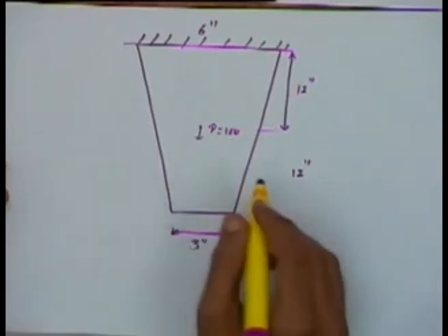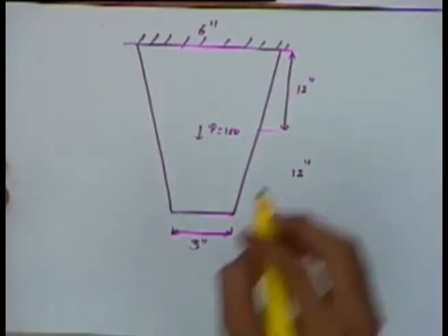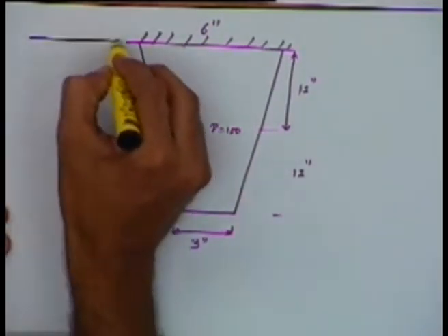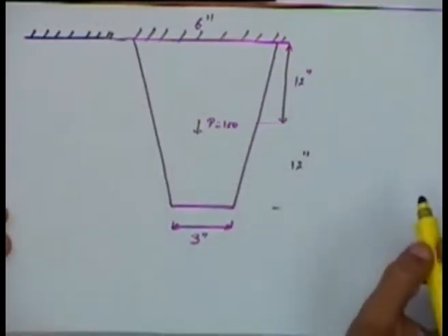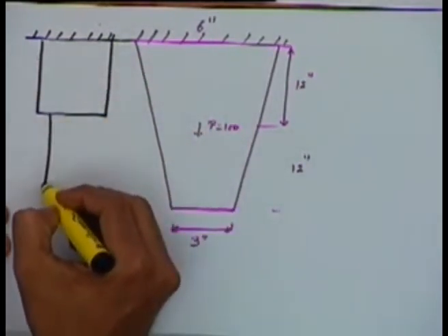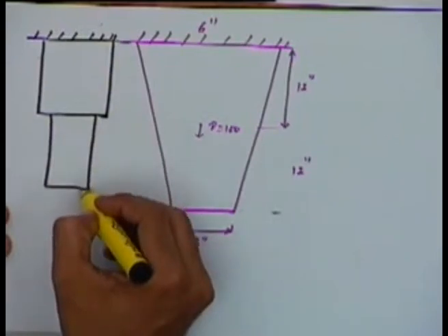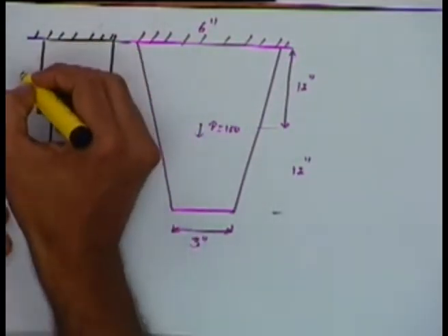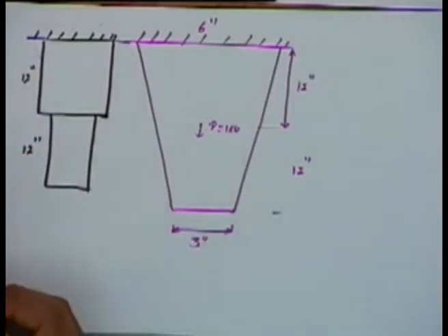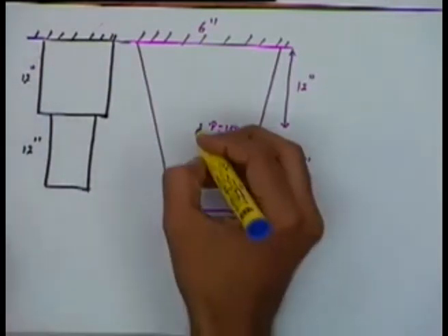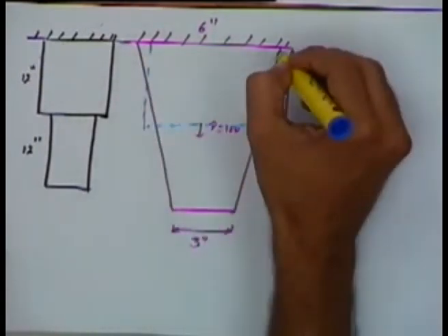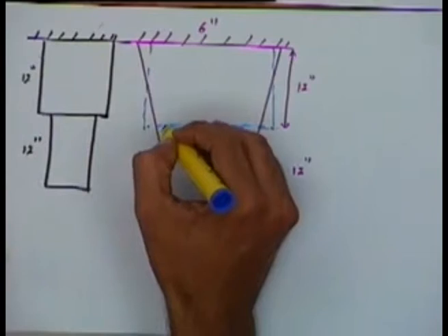Okay, if I take an object like this, I can approximate it by two elements which look something like this. Okay, the length of the first element is 12 inches, second element is also 12 inches. Okay, essentially what I have done is, at the place where this point force is acting, I split it like this. I have taken one element here and the second element somewhere here.